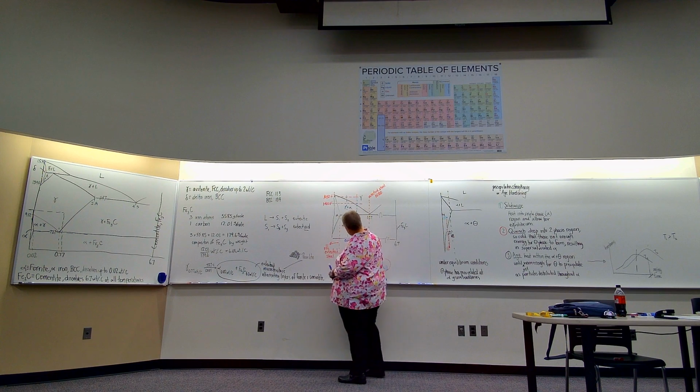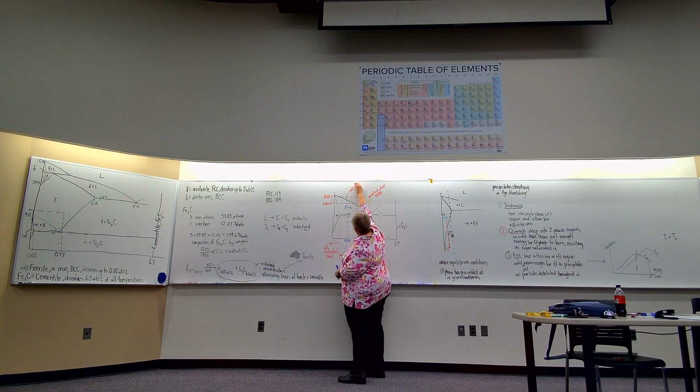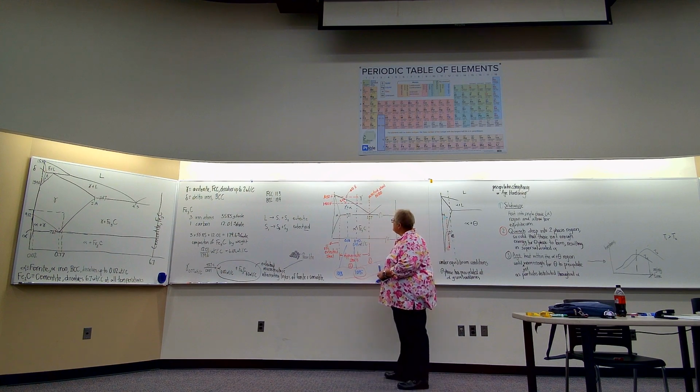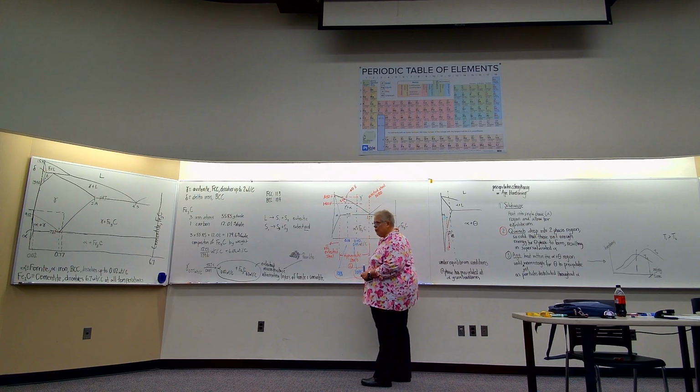So heating this 1018 to 1650, I'm going to have all gamma. Heating it to 1450, I'm going to have gamma and proeutectoid alpha. But my 1040, 1045, both temperatures will be all gamma. We should see a difference when we compare this and this in our ultimate product. And then, of course, we're going to heat to those, and then we're going to quench.